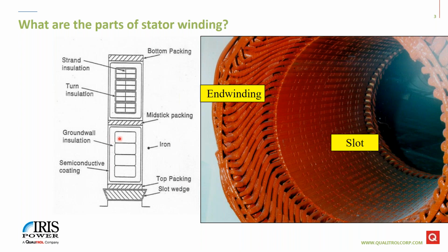That's the most common material today, where the epoxy glues those mica tape layers together. And the reason why that's there is because, of course, this copper is at high voltage. If it comes in contact with the stator core, which is at ground or earth potential, you'll have a phase to ground fault. Okay, and phase to earth fault. I've got to be bilingual here. And so what happens is, of course, your motor or generator would trip out. So we don't want that to happen.